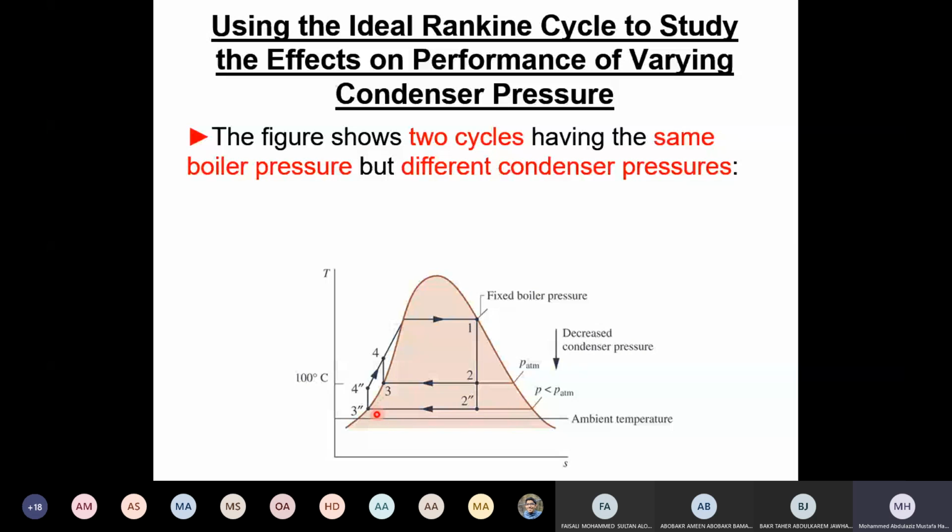As a matter of engineering, when you be an engineer and you work this cycle analysis, you neglect all of that here. But the limit here is look at that. How are we going to do the cooling here? How do we cool this here? We cool it by water from the atmosphere, the ocean or the river or something like that. And therefore, we cannot reduce this below the ambient temperature.